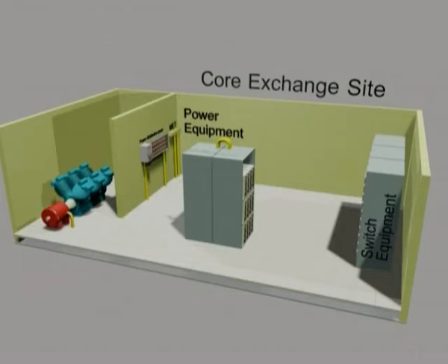In order to supply uninterrupted power to the switch, there must be some sort of backup system. The backup system could consist of banks of batteries connected together and supplying the necessary DC backup capacity. Batteries, however, have a finite capacity, and if the operator needs to provide a continuous service, then perhaps a diesel or petrol generator may be needed to supply uninterrupted AC to the distribution box.